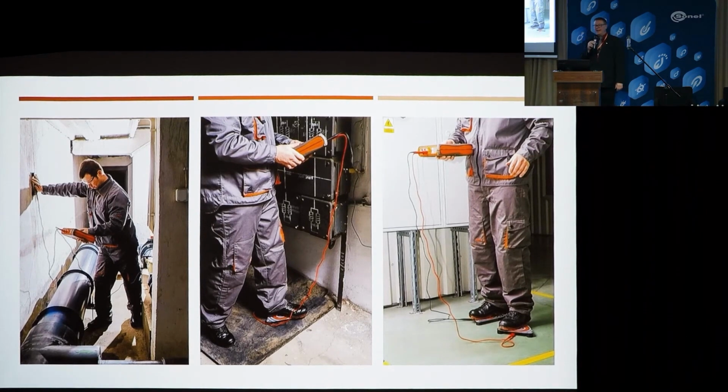And the last photo shows testing the surface resistance of the material the floor is made of. Here, to do that, you need two probes. They are placed 10 centimeters apart. You have to stand on them, and then you can carry out that measurement. This is actually a section of our floor at the company.